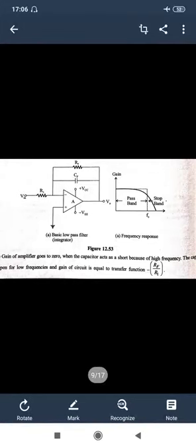Hello students, in continuation of our previous lecture, I will explain here the filter circuits via operational amplifiers with some elements like resistors and capacitors. So here we will first discuss the low pass filter circuit. In a low pass filter circuit, at a particular cutoff frequency, we pass the frequencies, and above that cutoff frequency we attenuate the frequencies. That is called the low pass.